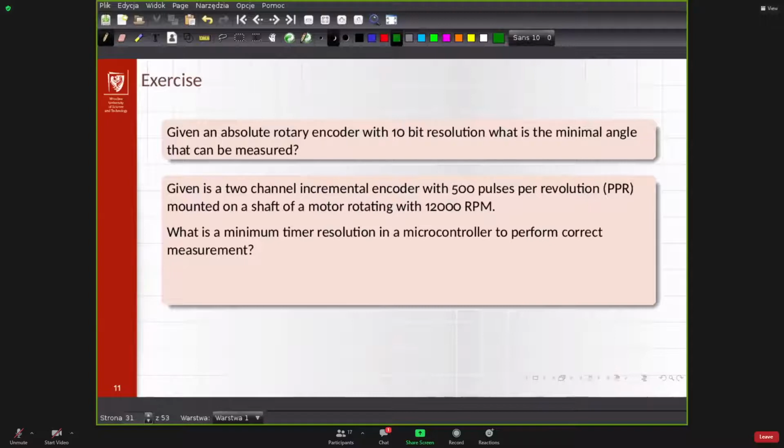And that's the timer that is 17 bits. And if you want to do it by your own procedure, because sometimes some people use directly the inputs of the microcontroller, then you need to have all the procedure finished in, that will be 10 microseconds, a very, very short time. Is it a realistic case? Okay, maybe it's not a common incremental encoder.